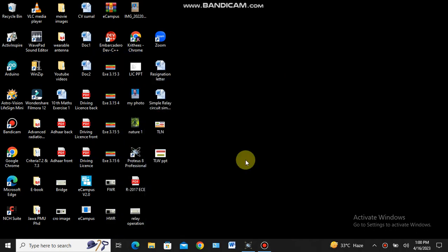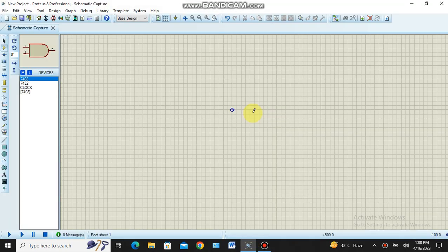In this video, I am going to explain how to verify the digital logic gates truth table with the help of waveforms in the Proteus Professional schematic capture simulation. So for that, first I have to place the AND gate, 7408.